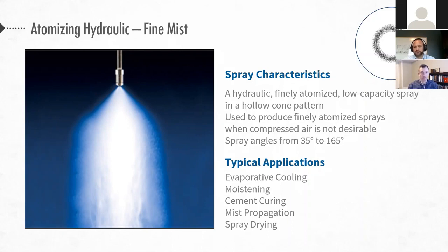And then the higher pressure nozzles, again with water, you might be looking at a few thousand psi. If you go to something that's more viscous, you might need to go up to 10,000 psi or switch technologies, like we're going to go into in the next few slides, to try to atomize a material that otherwise would not atomize.